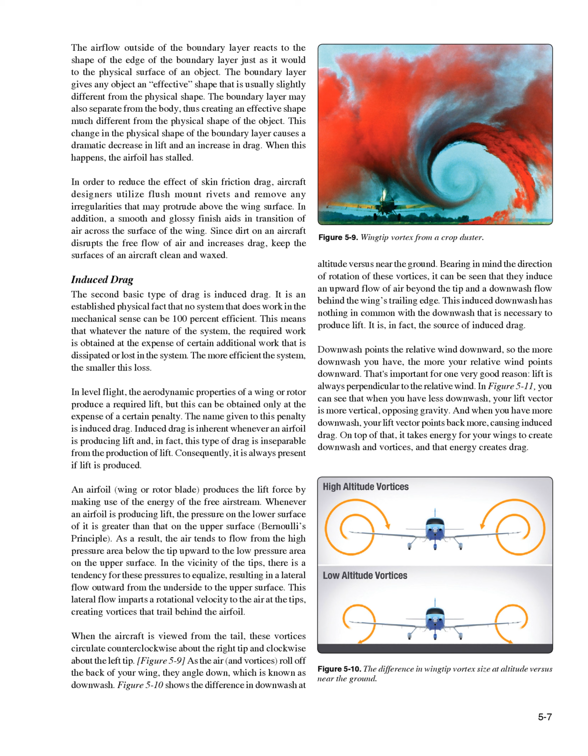In level flight, the aerodynamic properties of a wing or rotor produce a required lift, but this can be obtained only at the expense of a certain penalty. The name given to this penalty is induced drag. Induced drag is inherent whenever an airfoil is producing lift and, in fact, this type of drag is inseparable from the production of lift. Consequently, it is always present if lift is produced.